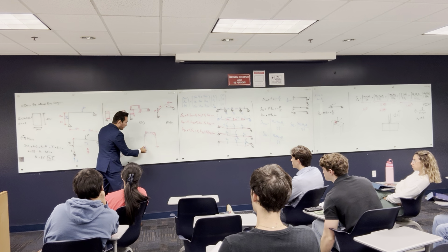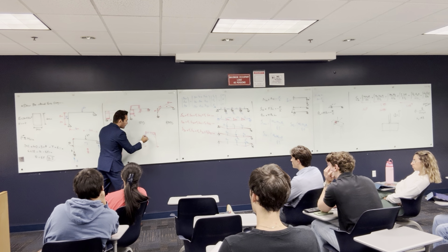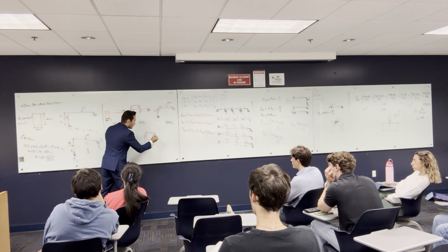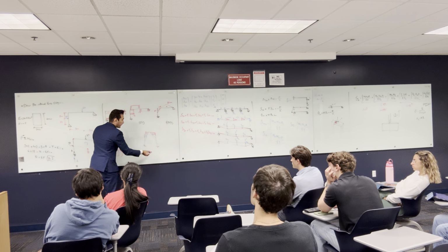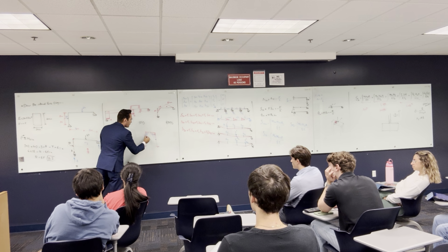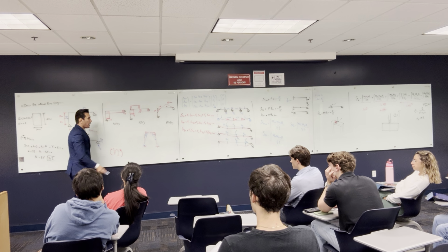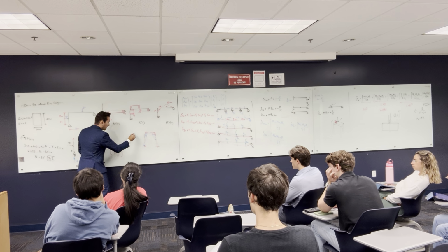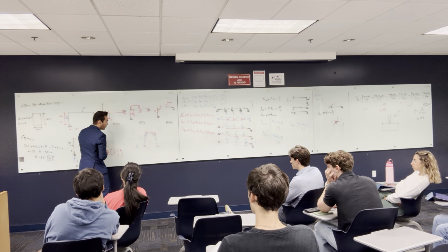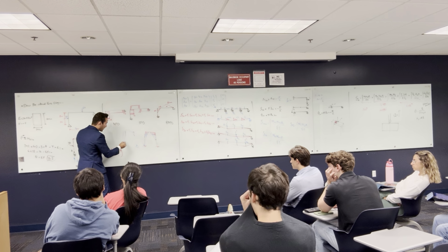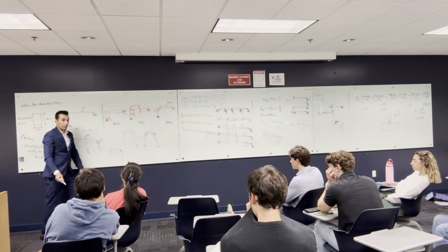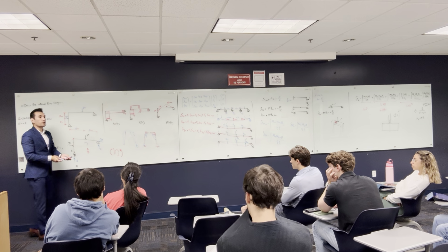But this is fixed, and I need to counter this bending moment, so you're going to have some bending moment, something like that. Because this is a fixation, this is what the final bending moment looks like. If this is hinged, with a hinge here and a hinge here, the same problem is going to be something like this, but the bending moment is going to go to 0. Because that's how you sketch the bending moment.